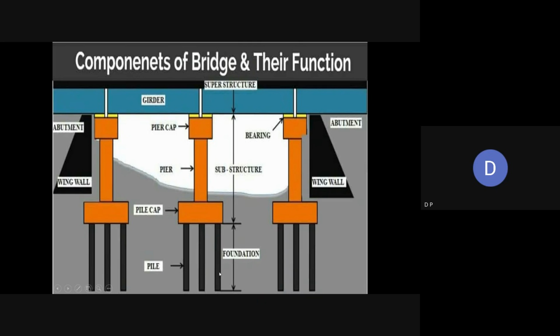So see this particular diagram for the bridge components. If hard strata is not available at lower depth, then we will go for pile foundation. Or if the hard strata is available at lower depth by open excavation, then you can do excavation also.